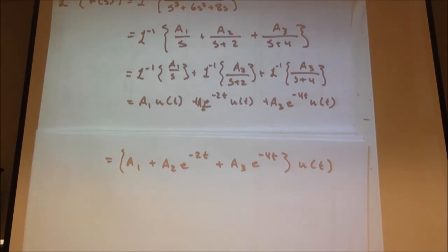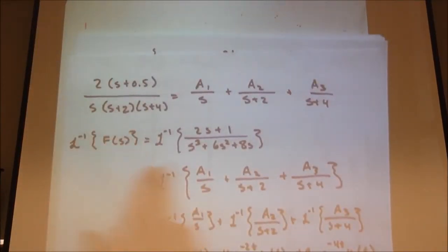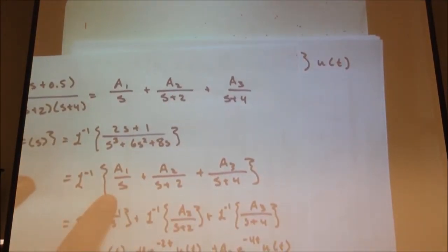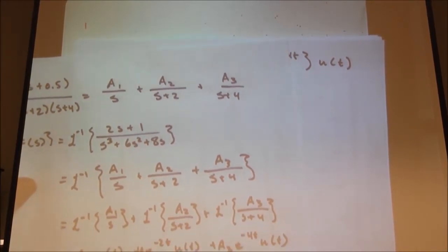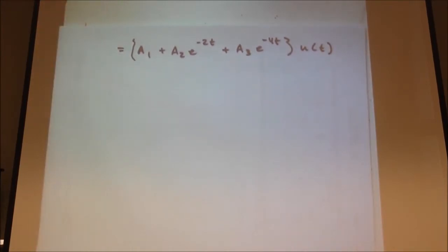But that's what we want to do. So if we can get a function for our circuit that's characteristic in this form, we can go through this process with the partial fraction expansion. We'll find the coefficients in just a second, take the inverse Laplace transform, and lo and behold, we have our circuit response. So we don't even have to go to the differential equation. That makes us happy, perhaps.